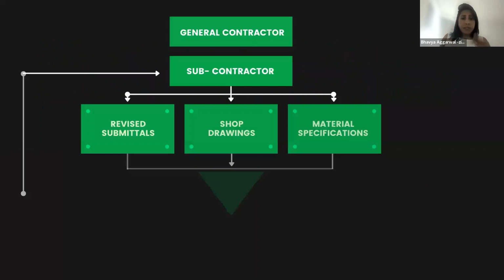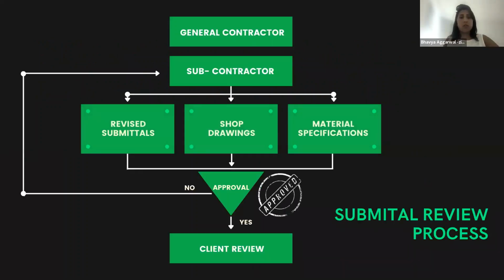So we've talked about how the whole submittal process is time consuming. But what is the process? This is a very simplified version of the process. Typically, a general contractor will wait for subcontractors to share submittals, and they could be multiple things, right? They can be mock-ups, shop drawings, material specifications, everything that would enable the construction to get started and get certified that, okay, this is good.